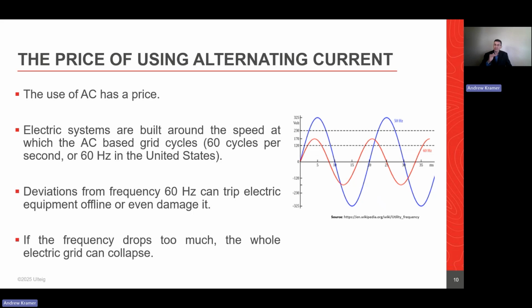So that's pretty much where the grid itself can be in major trouble. It's when you're watching the frequency and you start to see it drift below. You might think, looking at it sometimes, like maybe you've seen your lights flickering or something along those lines, and you think, oh, that means the frequency's dropping. If the grid actually dropped to the point where you could see that much flickering, it would have collapsed. That's actually a local phenomenon often associated with voltage. So normally, when you start to get below 60 hertz, even a small amount, 59.99 or 59.9, a lot of times that means the grid itself can be in trouble.